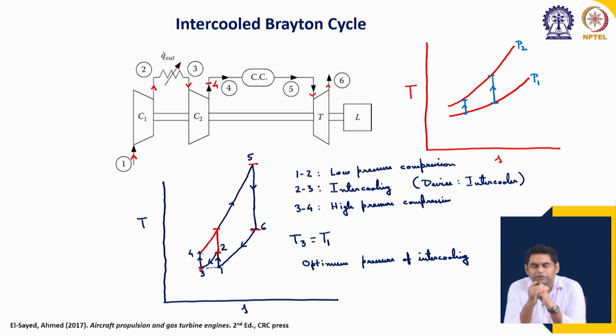A couple of points that we should remember here: because we are adding a heat exchanger and there is heat exchange between liquid water and air, the size of the heat exchanger is quite bulky as compared to all the previous processes. Regeneration can be done at high speed, both the gas flows can occur at high speed, and there is no external source of any additional fluid needed. Similarly, in reheating also combustion can occur in a small footprint.